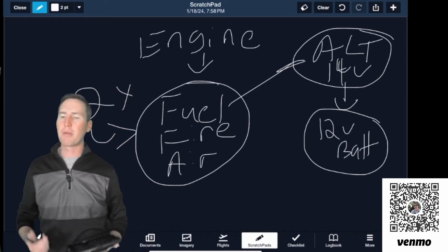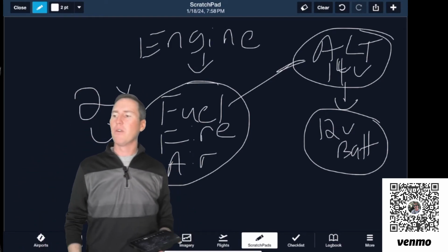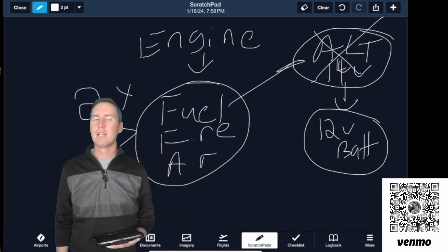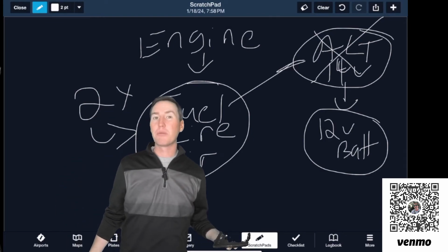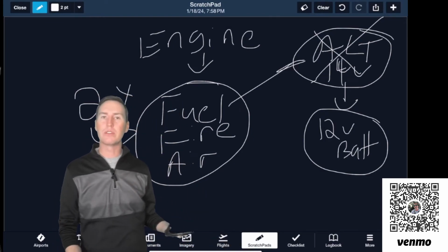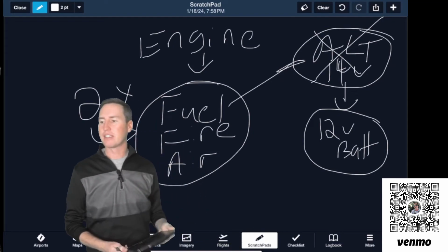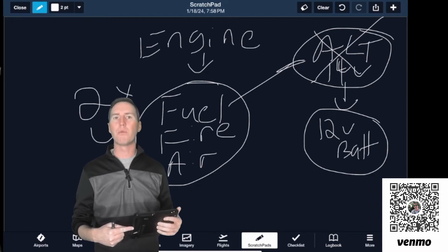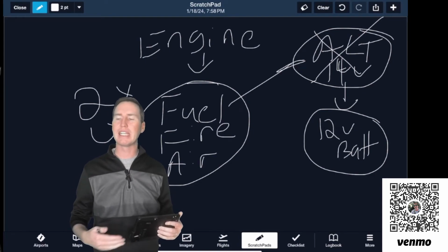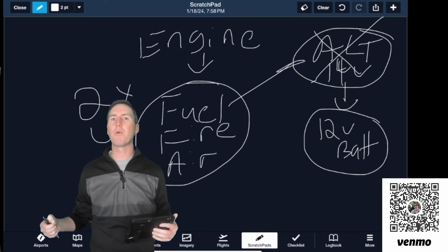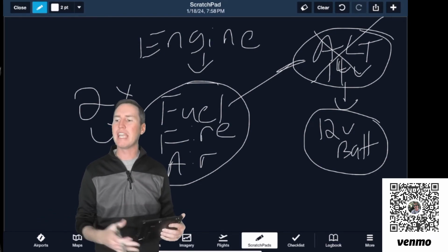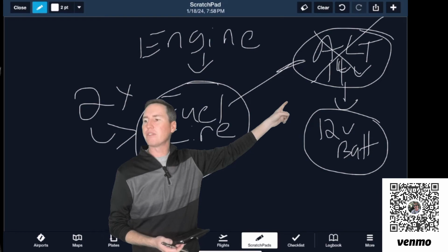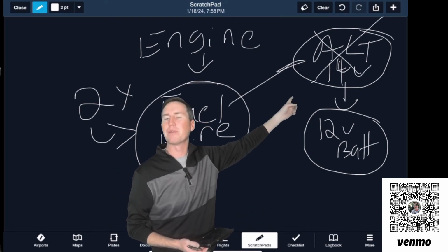charged. Now, when we talk about systems, equipment, and malfunctions, okay, what would happen if we lost the alternator right there? What's going to happen? Do we lose all electrical power? No, you just lose the charging source. So it's kind of like this iPad. You can see this iPad right here. When you have it plugged up into the wall, that's plugged up to the alternator. So it's getting a charge, right? If you unplug it from the wall, then you have taken it away from its charging source. So that's the same thing that's happened here: I've just unplugged the battery from the wall, if you will,